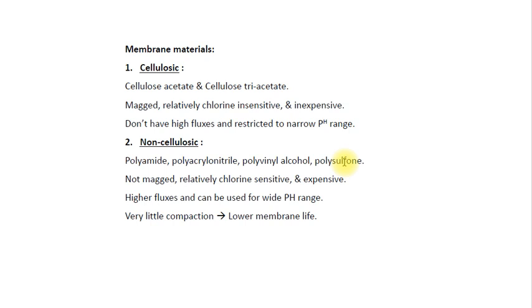First is the polyester texture, which has very high porosity and large pore size. Above that we have a very thin layer of polysulfone ultrafiltration membrane, which has micro size pores and provides high strength to the material. Then there is a very thin layer of polyamide. That polyamide will provide the separation and allow the water molecules to transfer from the mixture. So the separation occurs due to polyamide only, and the other materials provide mechanical strength to the polyamide layer. Generally the membranes used nowadays are polyamide membranes.